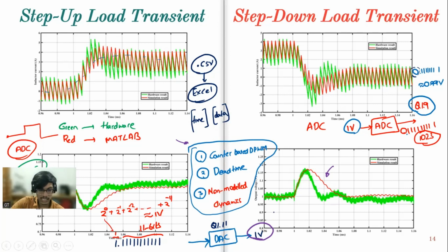When we say digital implementation in FPGA, everything is in bits and numbers. We are operating in binary, so it is zeros and ones. So if we want to take 1 volt to the FPGA, it is not just 1, because 1 means 0 or 1. If we want 1 volt, it should be some equivalent digitized number.